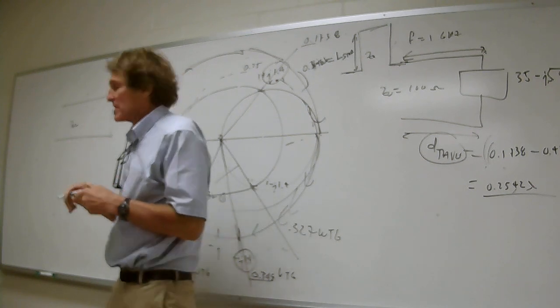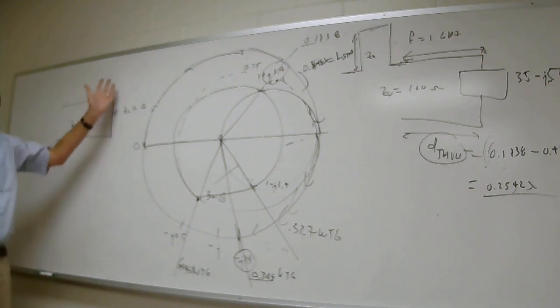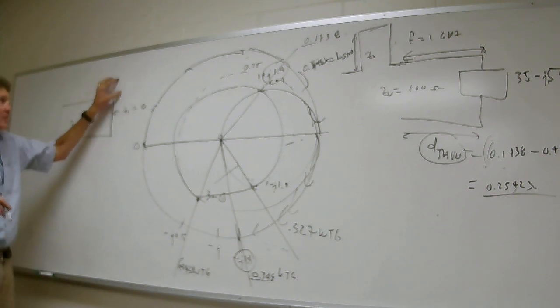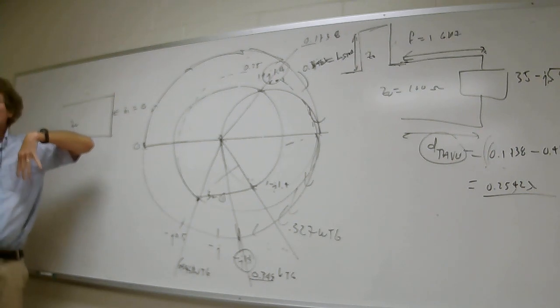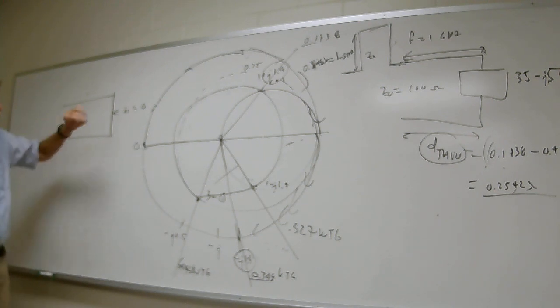The reason I don't like it, you see how they're shorted right here? That short is probably going to be shielded in the real world. There's no plus to minus voltage hanging out here that could interfere with nearby circuitry. Anytime you have a voltage difference at the end, dangling like that, anything nearby could be affected.